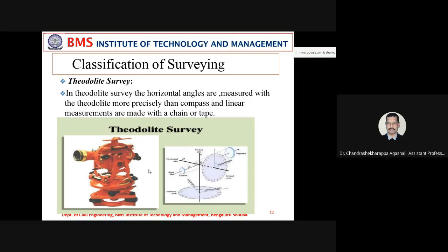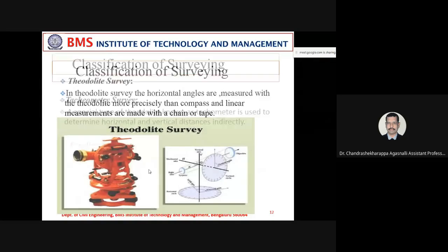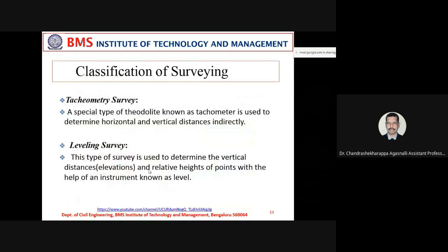It has the compass function, the angles, the vertical angle, horizontal angles, and the distance. No need to measure with the tape, no need to take the compass. That's called a total station. You just need the ranging rod and your staff, and more precisely the prism to get the reflection.